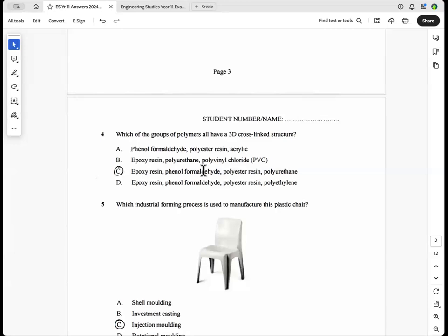we'll be doing it next year when we do composites in aeronautical engineering. The Nomex honeycomb between two layers of carbon epoxy layers is that honeycomb is paper, which has been impregnated with phenol formaldehyde.